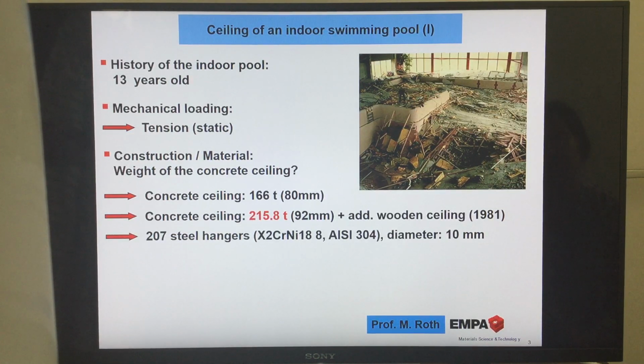So it's a low carbon, 0.02 carbon content. Then 18, that means 18% chromium and 8% nickel. Of course, we know due to this alloy, the steel is then austenitic, and it should be protected against corrosion. And that's the American designation, 304.